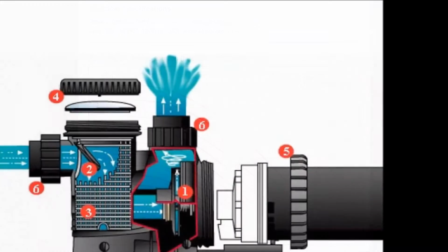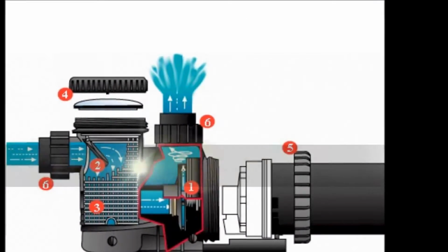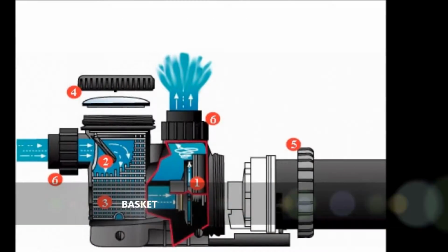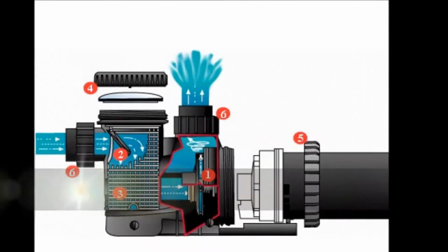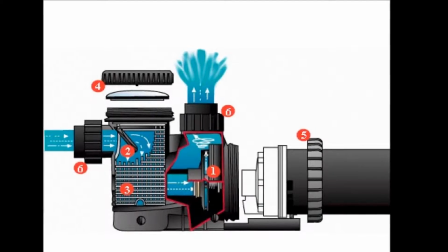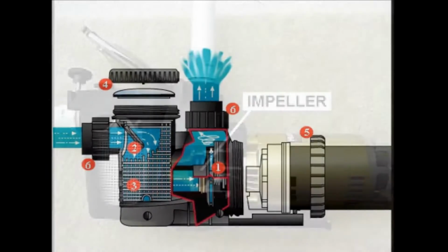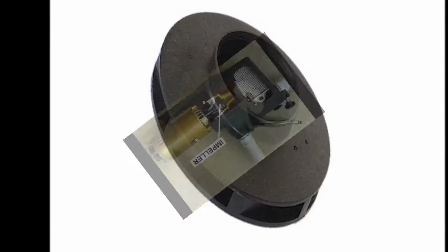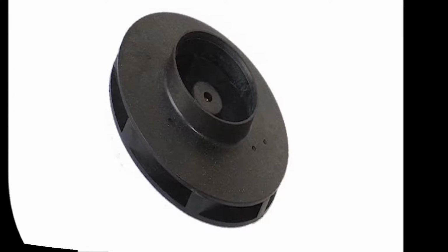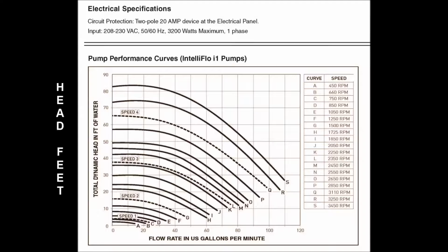Pumps do two things. They produce pressure, referenced as either PSI or head feet, and they suck and push water, but not both at peak performance output at the same time. A pump's impeller is designed to provide the benefits of a specific head-foot measurement of pressure and a specific GPM flow criteria.